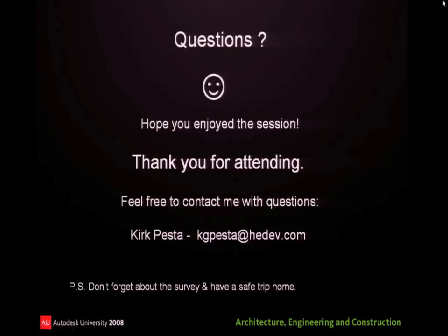Any other questions? The question is, do we have the other disciplines linked into each other's models? The answer is yes. Whatever Revit models we have available, whether it's structural, architectural, or electrical, we would have them linked in, and if we need one in that view, we would have it turned on and use it for coordination in those working views. They would all be loaded. Well, the structural, it depends what we're doing in the view. But yes, it would be available.